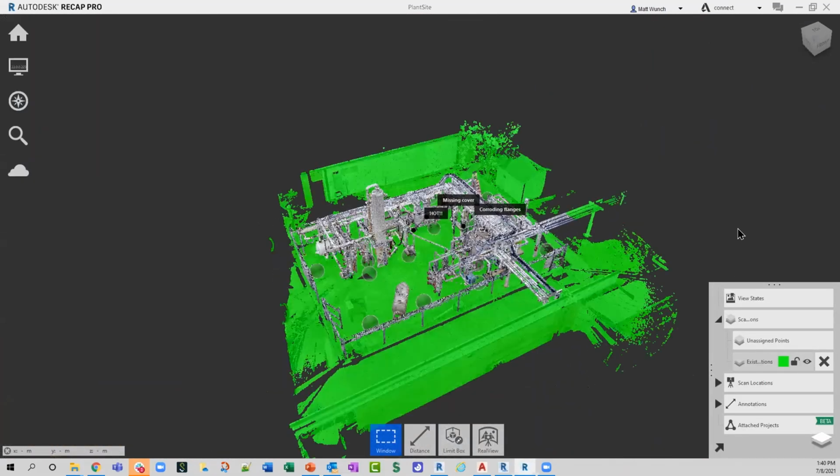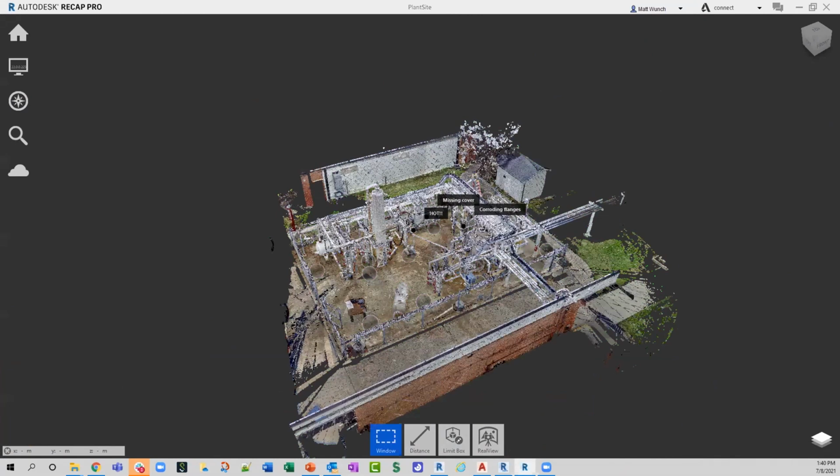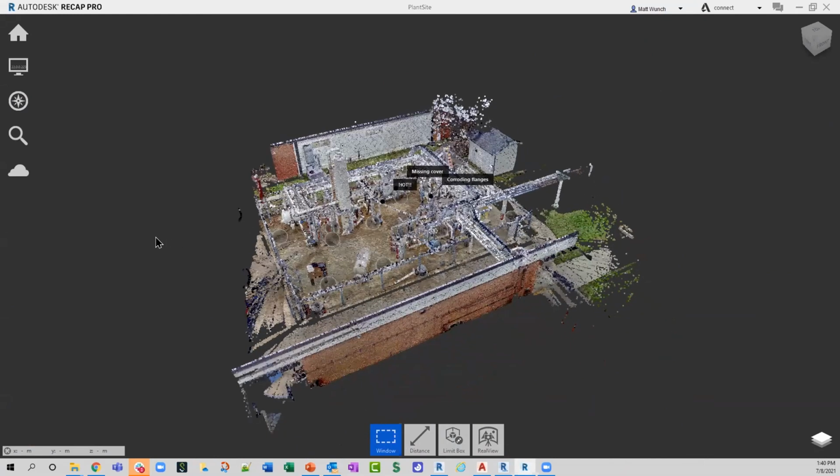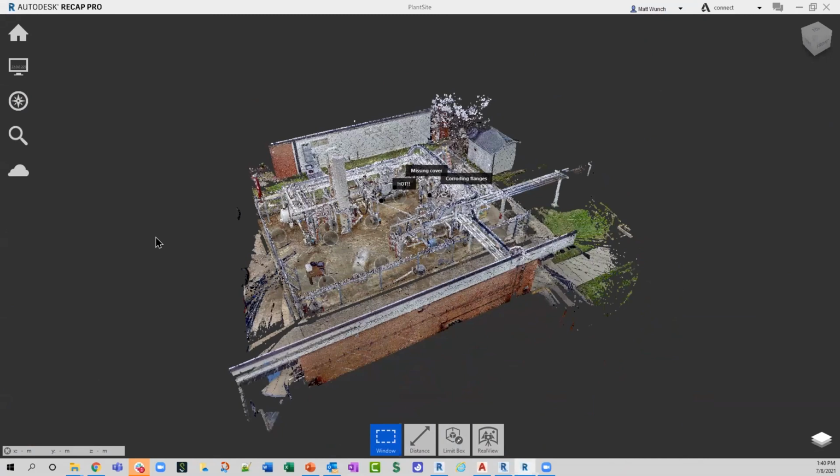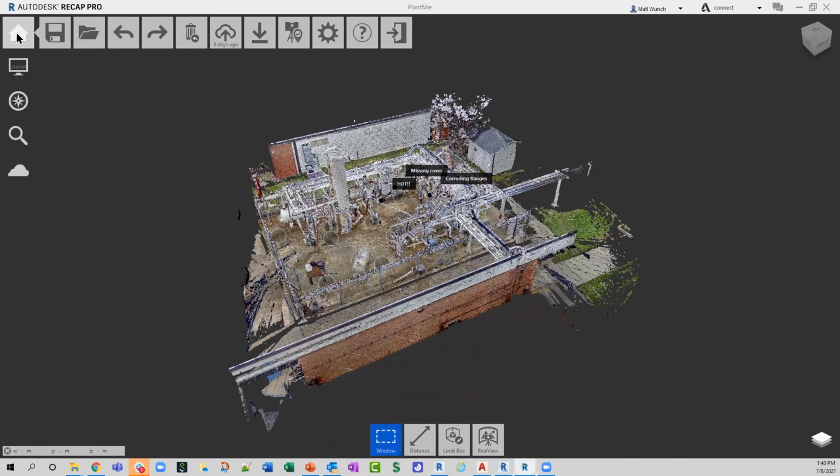No problem. I think someone on YouTube had asked about increasing point density for the scans, for example, which I believe would be done on the scanner end of things. Is that correct? Correct. Yeah. If you wanted to go the other way, so making these point clouds a little bit more lightweight, whether you bring them into Civil 3D, Revit, AutoCAD, Inventor, I mentioned that point cloud that I showed in Revit, that was kind of like everything was bound into it, right? Yeah. So there's an option here when you export this.